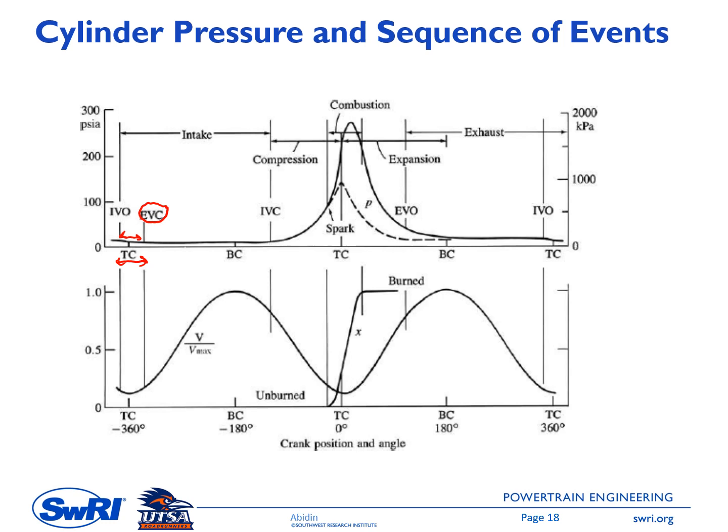Okay, so we have intake valve closing at this time. The period between intake valve opening and intake valve closing is called the intake process or intake stroke. And you can see here that the intake valve closing is several degrees or tens of degrees after BDC. It is not right at BDC. You can see here, this is the BDC point. Once again, the reason for having this is we want to maximize the fresh mixture entrance to the cylinder.